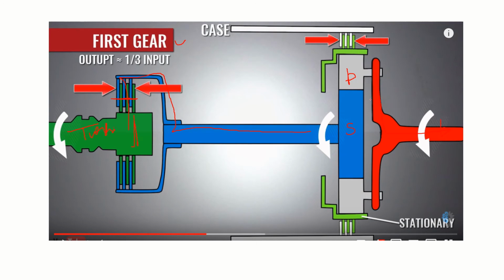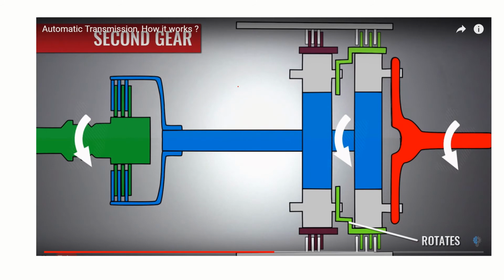Okay, next. Let us say, how do we get the second gear? Again, this is driven by the turbine. You lock this. When you lock this then this will become a single part. As this shaft rotates, this has to rotate, correct? Then this will drive the shaft. Yes, this will rotate. This will rotate. You can see over here what has happened, right? This part is driving this.